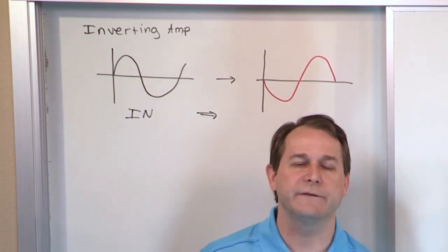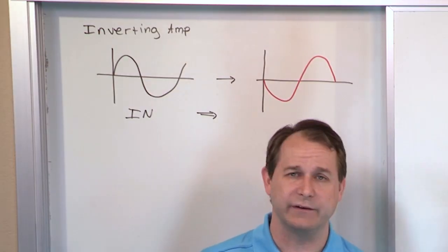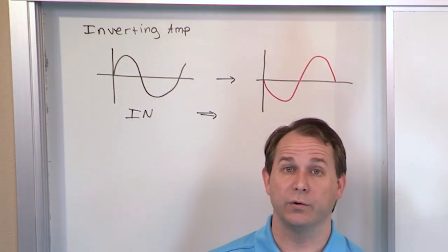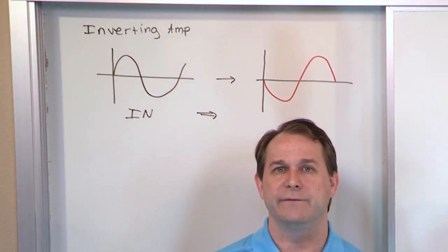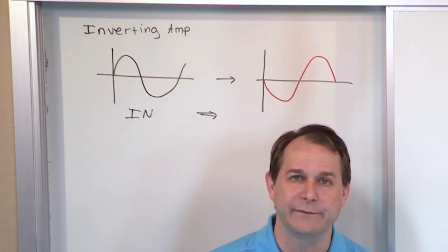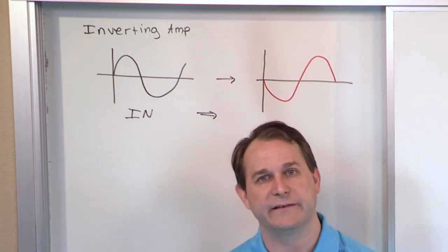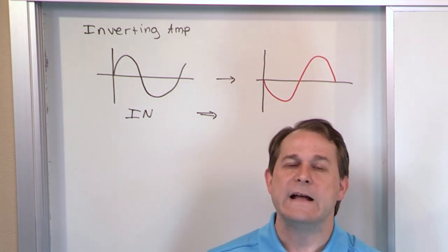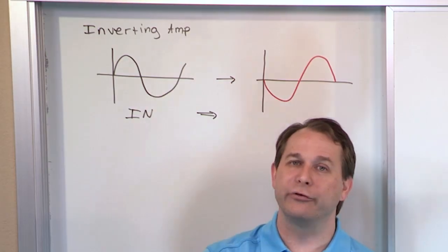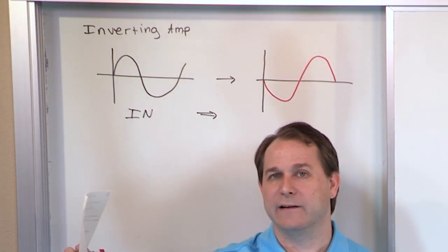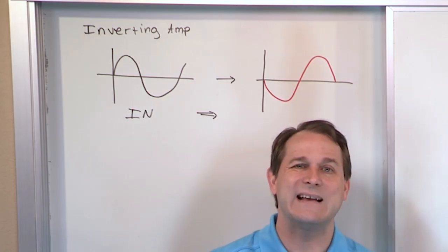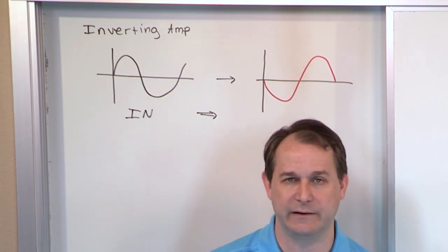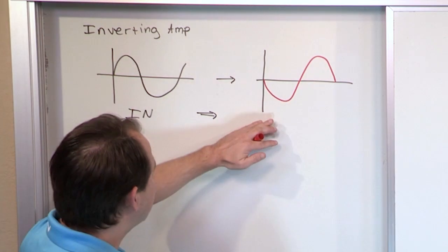That's why in all of the circuits with DC sources, when I sent positive 1 volt in, you got a negative voltage out with the inverting configurations before. Or if I sent a negative half a milliamp in, you always got a positive value out because it was inverting. You can also make the signal bigger or smaller, you can amplify it in the larger sense or the smaller sense, but always in those inverting configurations, the sign of the output was opposite of the input, just like I'm drawing for you here.